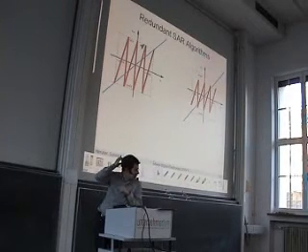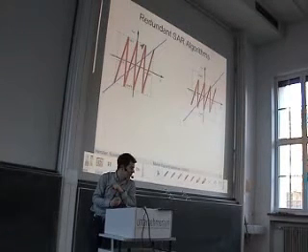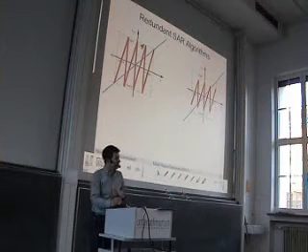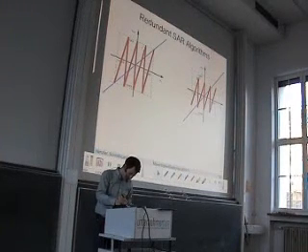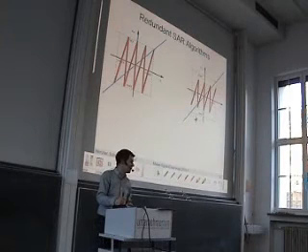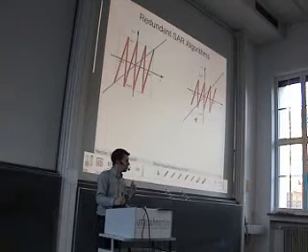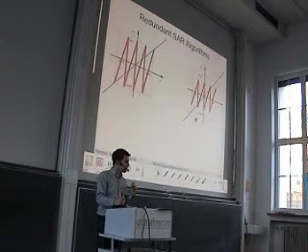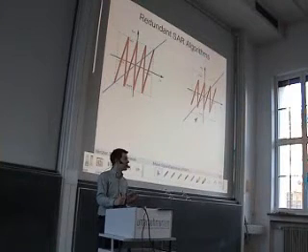This can be seen on the right-hand side. Here we have still these 3 thresholds, but you can see that the scaling factor is less. So we do not scale the residue back to full range, but we have a scaling factor that is smaller. So that's why I wrote in these pictures always A and not a factor of 2. A factor of 2 is the basic algorithm, but we can also choose another factor.